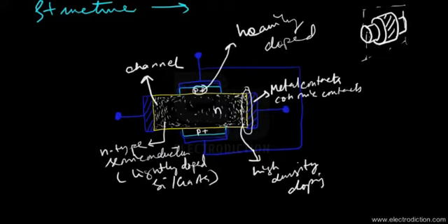So the doping concentration obviously is higher at the sides of the semiconductor, where it gets connected, or rather forms a contact, with the metal caps. Other than that, inside the N-type semiconductor bar, the doping is, as said earlier, very light, as the whole thing is lightly doped. So there you go. That's basically the structure of the JFET.